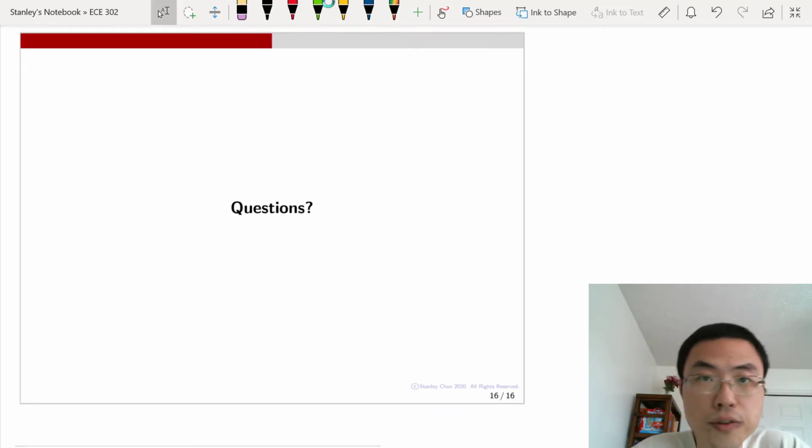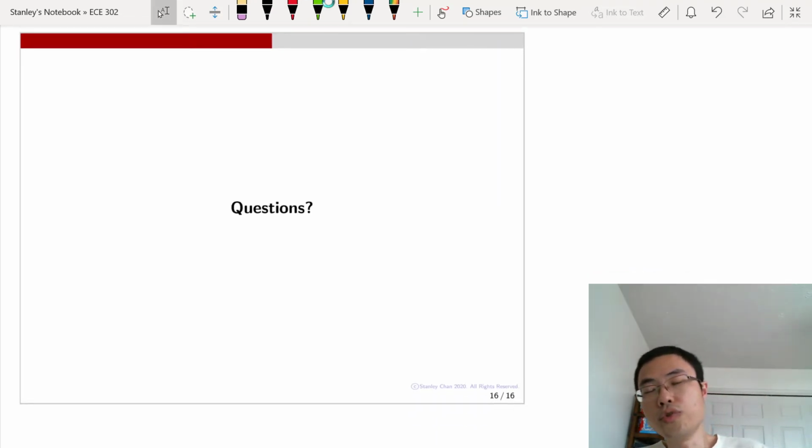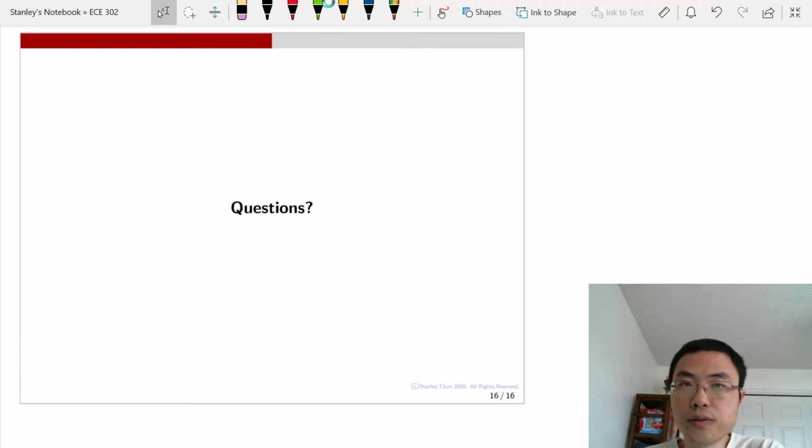All right, so this is the end of this lecture. We have introduced 3 concepts. The first concept is the mean function as the random process goes through an LTI system. The second concept is the autocorrelation function. As we see, it is a double integration that involves a convolution followed by a correlation. The third concept that we study in this lecture is the power spectral density. Remember that when you look at the power spectral density of the output, it's the magnitude square of your transfer function. And we also show an example of doing all these three together.